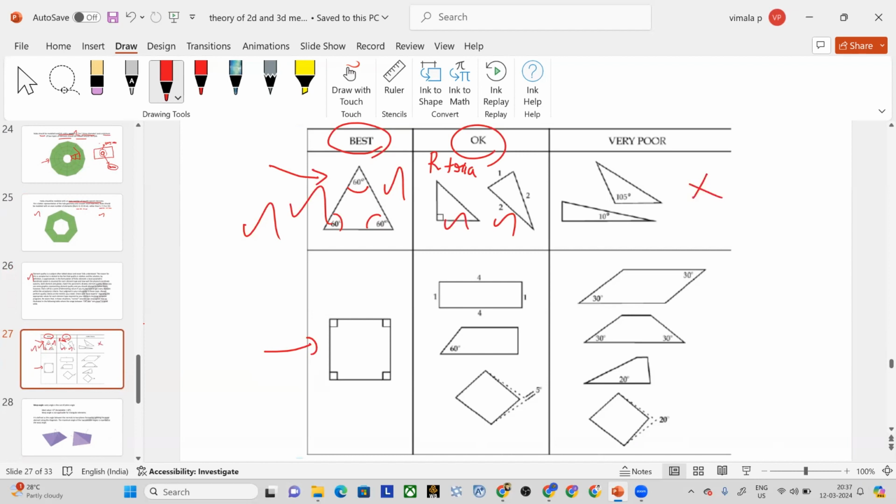If you are getting some meshed triangles, then you should actually remove these kind of triangular elements where you get a more acute angle or more obtuse angle. These kind of elements should be removed. Similarly, while doing the quad meshing, we actually want all the four sides to be equal, something like a square. We don't require a rectangle actually. That is the best mesh you can provide. And the included angles should be 90-degree.